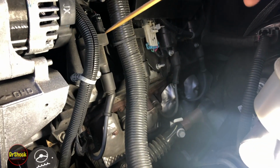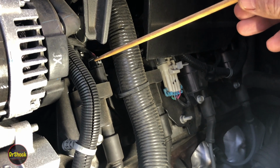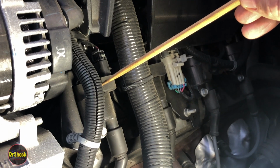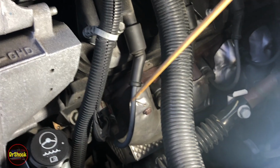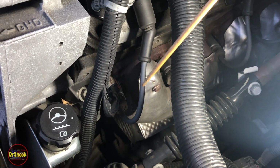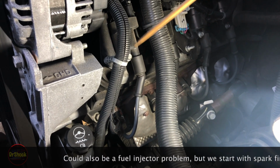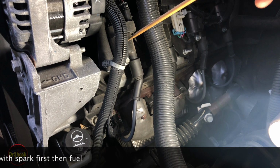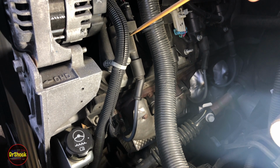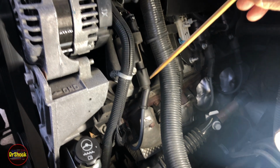So if we take a look at this kind of a hard fault, we either have a problem with the electronics coming from the powertrain control module into the coil, or we have a problem from the coil to the spark plug, which would mean the plug wire, or we have a problem with the plug itself. This is pretty straightforward. Is it going to be a problem with exhaust being plugged up or something? Can it cause that same code? Yeah, but not for a single cylinder misfire. At most it might be a stuck exhaust valve. But let's not go for the hard stuff. Let's get rid of the easy stuff first.